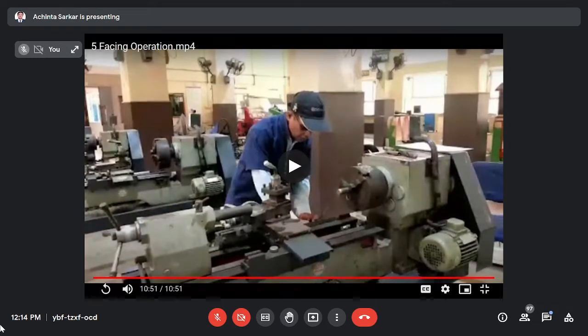Because during cutting, there will be a close interaction of the cutting tool and the workpiece all the time, so there will be friction. So we should select a type of material that has a low wear rate. Due to the friction, more heat will be produced, and some heat will be transferred to the cutting tool and some to the workpiece, so the cutting tool should withstand that much temperature. Okay, so here we are talking about a cutting tool material, that is high speed steel.